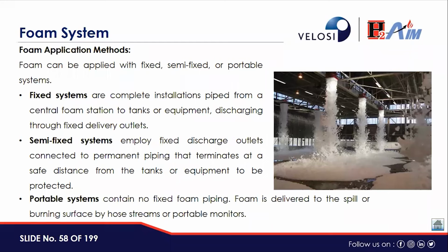There are different methods of application of this foam system. It involves fixed systems, semi-fixed systems, and portable systems. Fixed systems are complete installations piped from a central foam station to tanks or equipment, discharging through fixed delivery outlets. Semi-fixed systems employ fixed discharge outlets connected to permanent piping that terminates at a safe distance from the tanks or equipment to be protected. Portable systems contain no fixed foam piping. Foam is delivered to the spill or burning surface by hose streams or portable monitors.